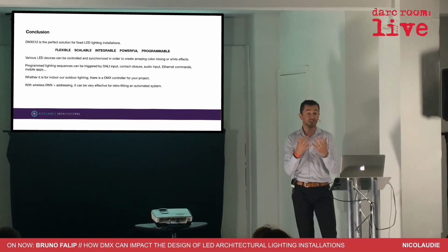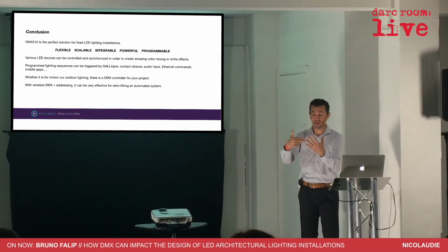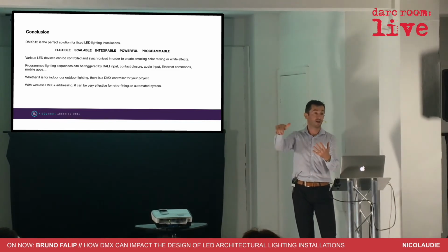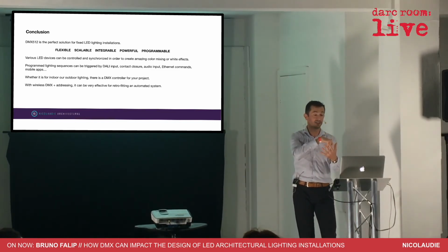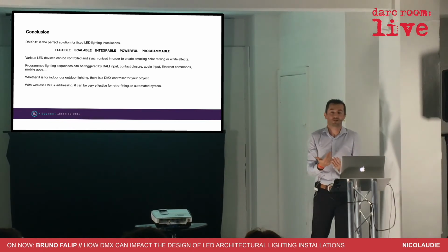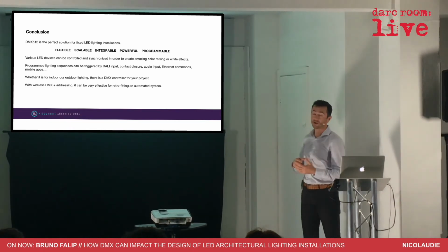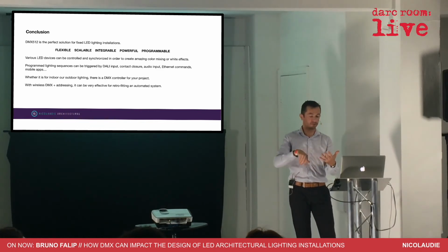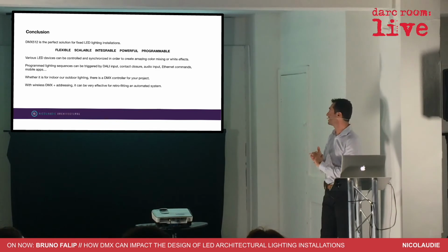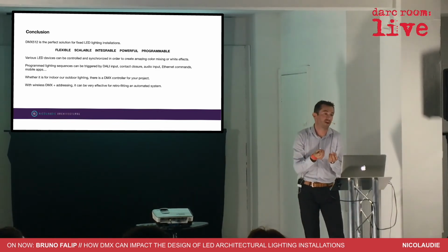And the basic of the wiring is that you go to one device, there is an input and an output. So it's a chain, and this is how it works, compared to DALI, which is a little bit easier to wire. That is a wire with a star, but the problem of DMX is this. This is the only problem, in fact: the wiring.